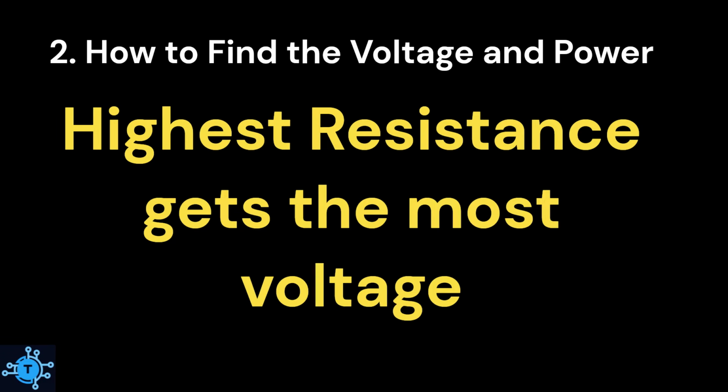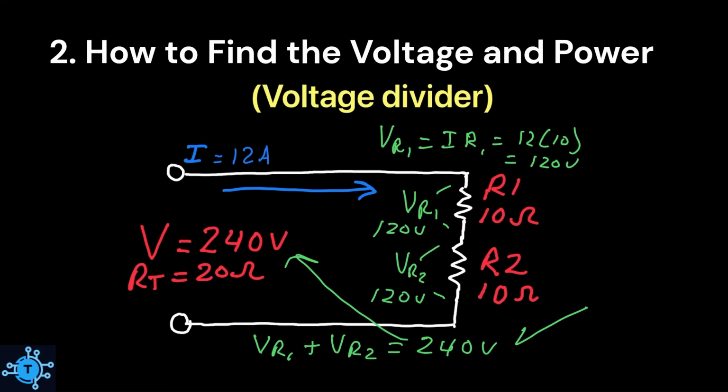In a voltage divider, the highest resistance will have the most voltage. Let's say, for example, that you were to increase the resistance of R1. If you did, the voltage across it would also increase. As you continue to increase its value to infinity, R1 would eventually have all of the 240 volts across it. That's how voltage dividers work, and it's one of the most important aspects about them that technicians should understand.